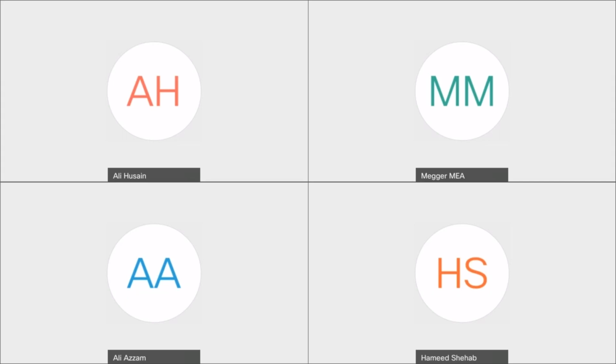Some circuit breakers, usually in medium voltage, it will be a little bit difficult to locate this position, either because it's very small or compact, or maybe it's internal and you cannot access it. In this case, not doing the timing or travel test is okay. But in breakers where you can do it, please do it. And we are here to provide help for you for that.